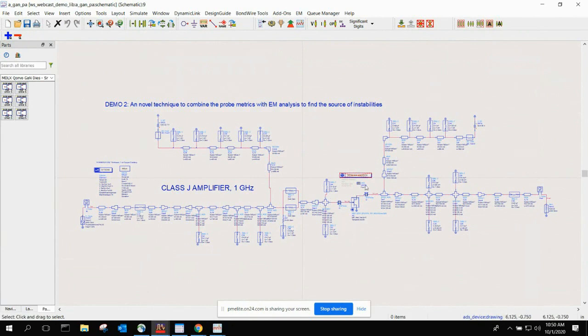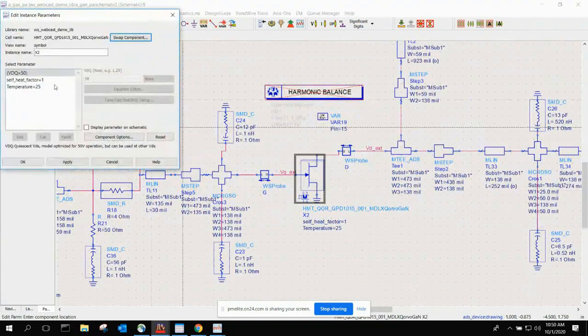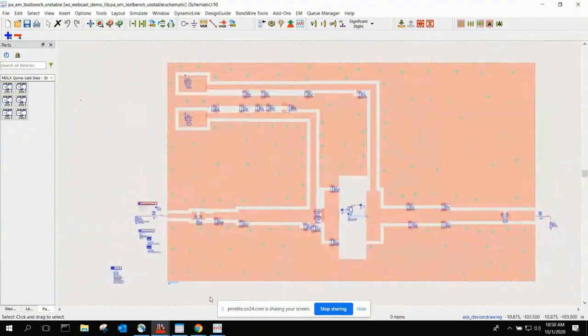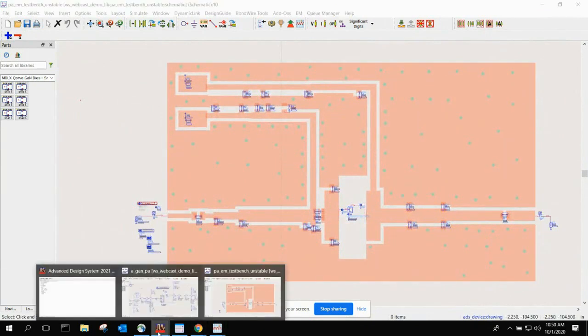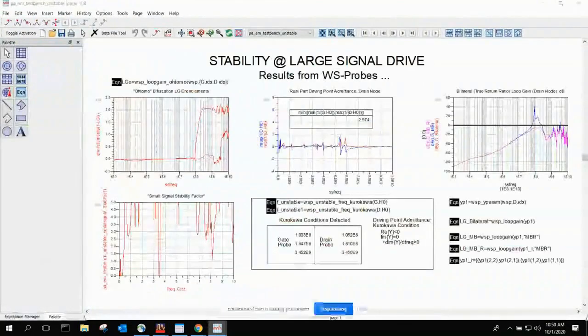So I've got this gallium nitride power amplifier here. This is based on a device from Qorvo and a Modelithics model. I can't go in and do a normalized determinant in the Modelithics model because I can't turn off the source. That's extremely common. And basically, what do I do? I build an EM structure. So I built an EM structure, and I put the EM in, and I found that the circuit was unstable with that EM. So let me see if I can find what happened.